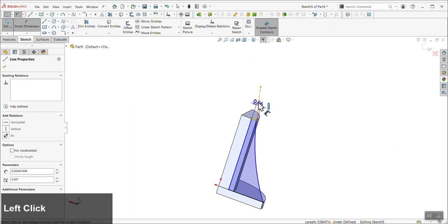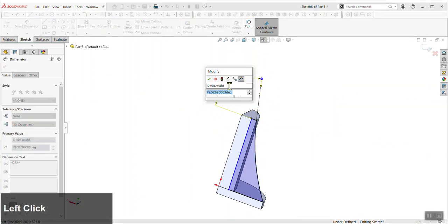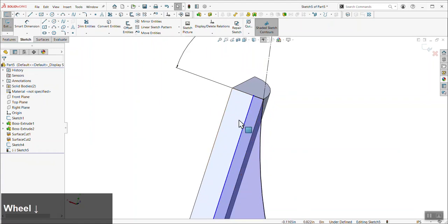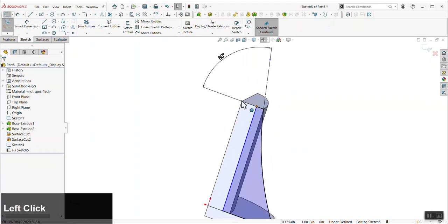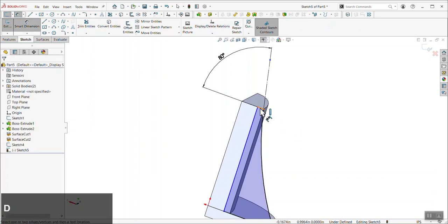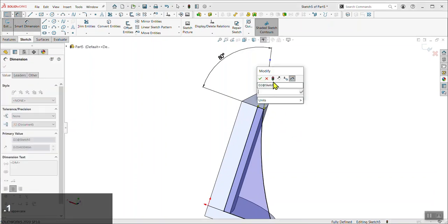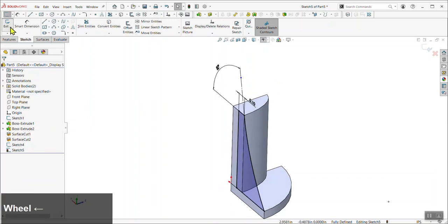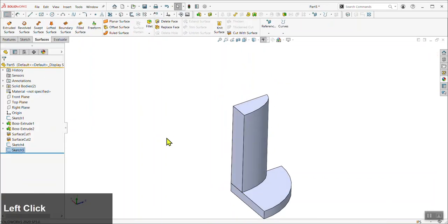So sorry, for construction, and then 80 degrees to the top edge of our shape. Again, somewhat arbitrary, but it just sets this curvature. It gives us full control. And again, the amount of overlap of the shape into the taller body, you can set that to be 0.1 inches, but it doesn't really matter. As long as there's some overlap in there, that's all that matters. And then I'm going to exit that sketch.